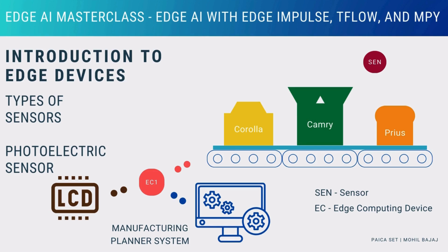For example, let's say you have an automation project for a Toyota manufacturing plant, which produces Corolla, Camry, and Prius. Let's also say that the demand is 1:1:3, or out of every 5 cars, 1 should be Corolla, 1 should be Camry, and 3 should be Prius, and in that order. Since these 3 cars have different engine and body parts, photoelectric sensors placed strategically can be used to identify the height or width of these different parts and ensure that the right car is being manufactured.